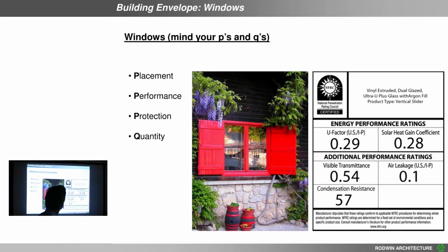So think of this like a percentage. This is the amount of solar radiation that comes through the film, the low E film. If you have a solar heat gain coefficient of, say, 65%, which is about the highest you can typically get, you're letting 65% of the solar radiation in, which on the south side, if you have proper size overhangs, is a great thing. It warms up your house in the winter, and the overhang blocks out the sun in the summer. On the east side, slightly lower solar heat gain coefficient, and on the west side, super low heat gain coefficient, like 20% or 0.2.